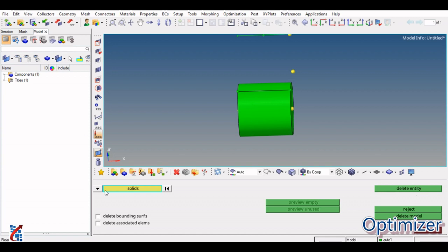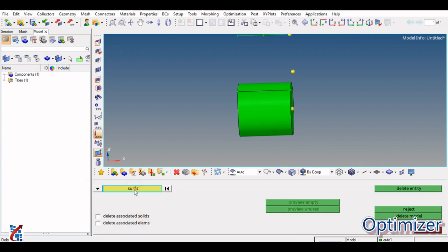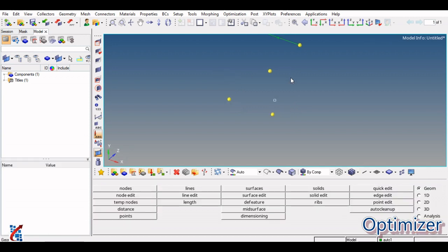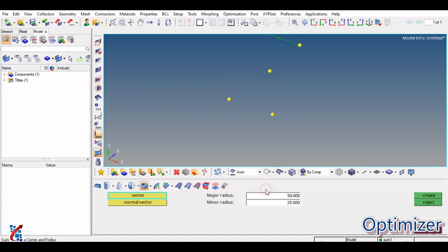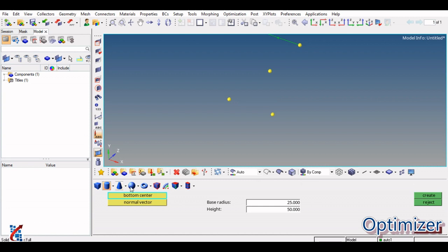Okay, and surfaces are again left there, so you can delete the surfaces also. Just go here, surfaces, and select displayed and delete it. Okay, so once you have created the solid, the surfaces are also there, you need to delete those also. Okay, we have deleted it. So other things you can check, like cone, sphere, and torus. All these are the same as what we have seen in surfaces.